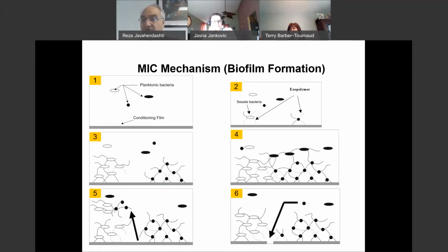When the partial pressure of oxygen is low, you create anode, and when the partial pressure of oxygen is high, you create cathode. And where you have anode, you get enhanced corrosion in the form of pitting. So with this explanation, I hope that you have found the mistake that I deliberately made in this slide.